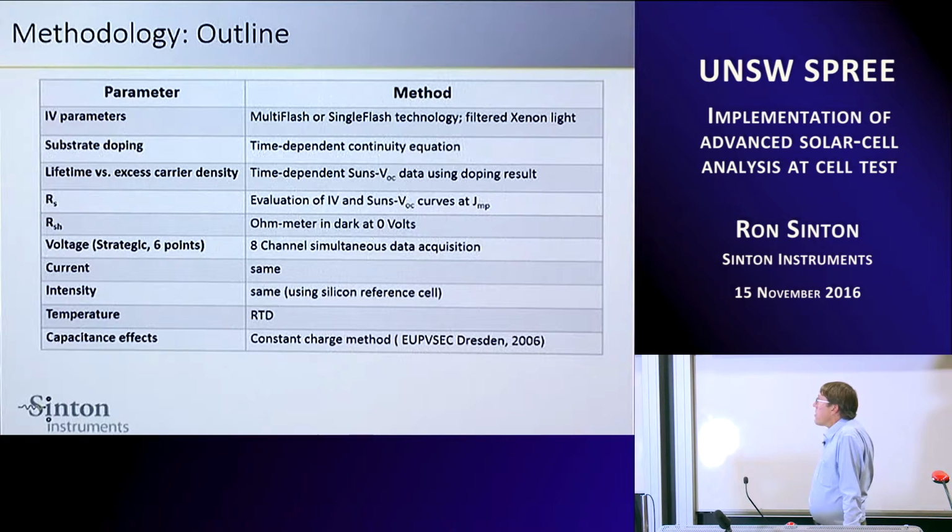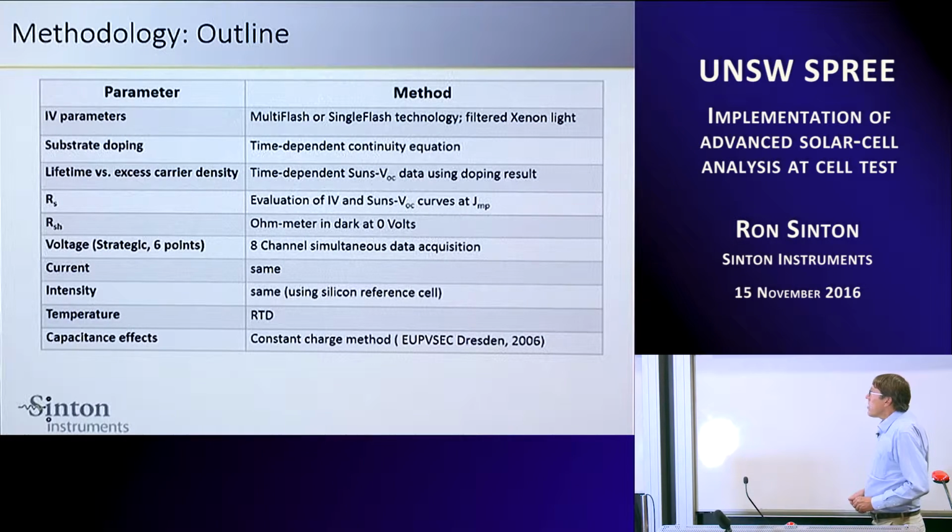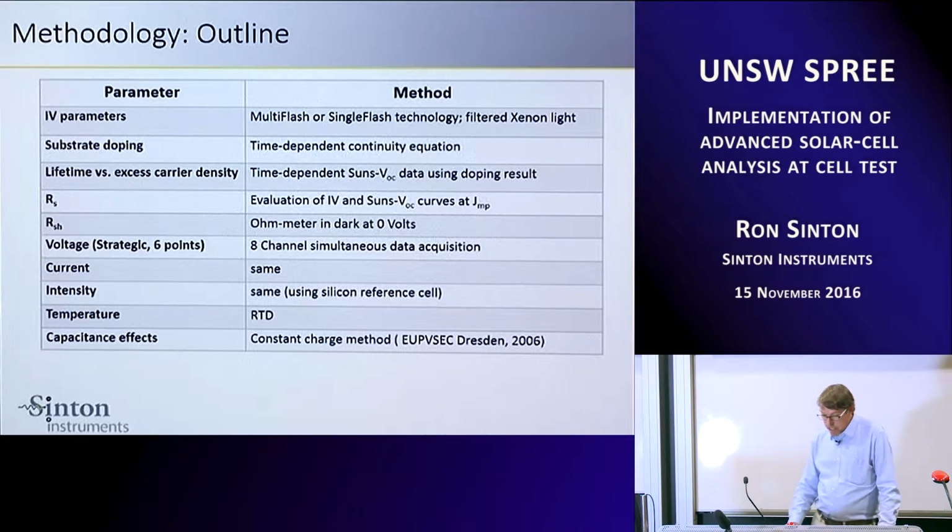We measure the lifetime versus excess carrier density from the Suns-Voc curve, RS from the Suns-Voc and the IV curve. The shunt in the dark, we use a good data acquisition system, basically temperature with RTD and capacitance effects I'll go into some detail on.